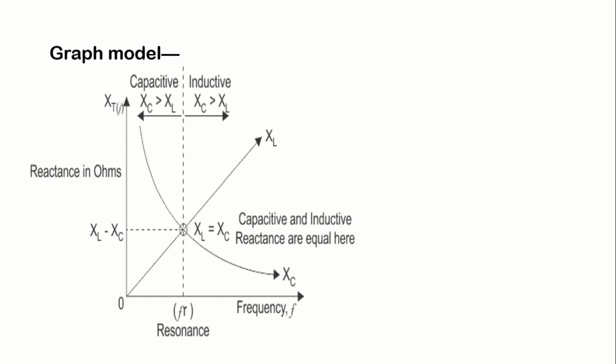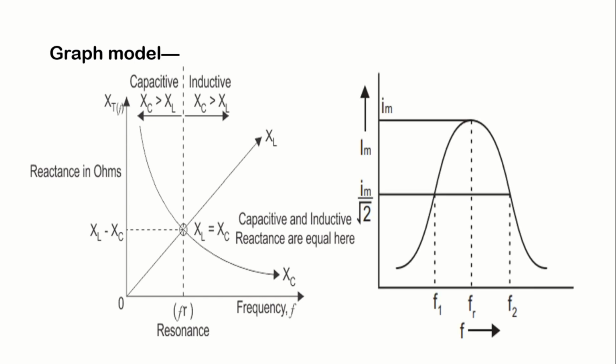Now by using this data we will draw two graphs. One graph is resistance versus frequency. The second one is gain versus frequency. And like this, with the help of the graphs we can find results like resonance frequency, quality factor, bandwidth,